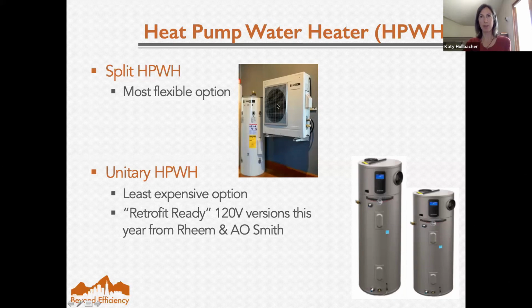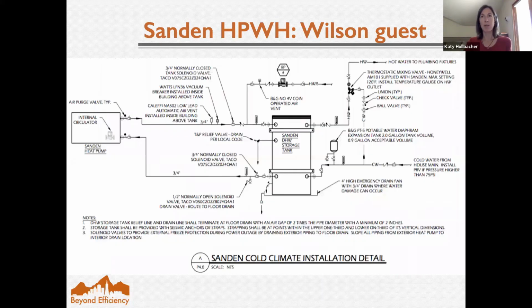This is showing the split systems with the outdoor unit and the indoor tank, like the stand-in, and then there are unitary systems with a heat pump connected, which potentially can be used indoors in our climate, as long as you're providing a high efficiency heat source to that space, since most of these unitary units tend to only operate in heat pump mode down to about 40 degrees. And this is a schematic of a stand-in design for the heat pump water heater that we won't get into here, but will be there in the slides if you want to check it out. And then Carol will be there to explain what all this means.